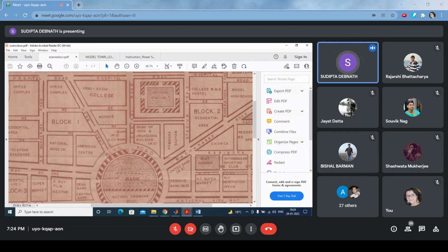Now one question will come. Suppose this road is 250 meters. So what to do? You start from any corner. From here put 100 meters, here 100, here 50. Otherwise, for 250 you can take 150, 100. It depends upon you. Normally, one road should be divided into some road segments. Normally you don't take segments less than 50; you take above 50, and also don't cross 300, maybe 250, 280, like that.